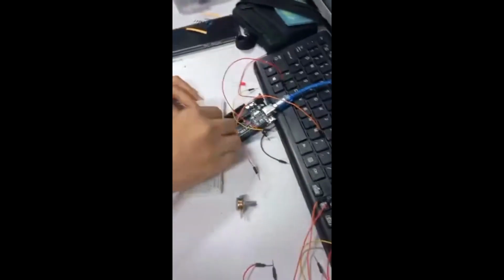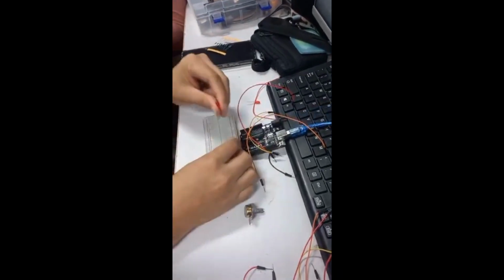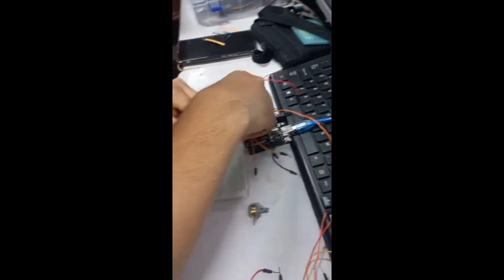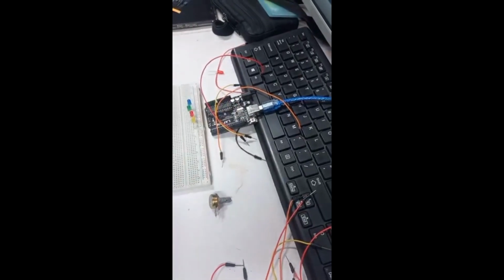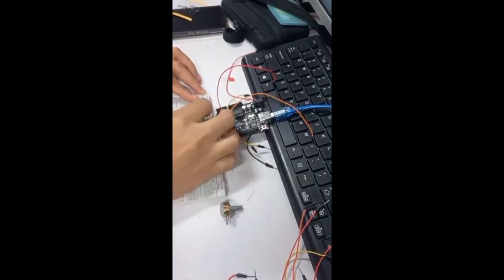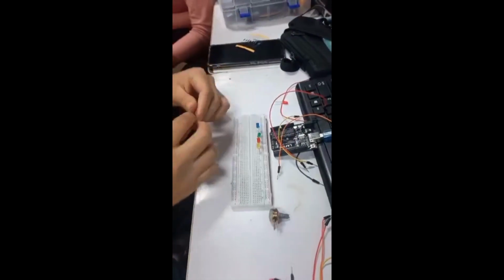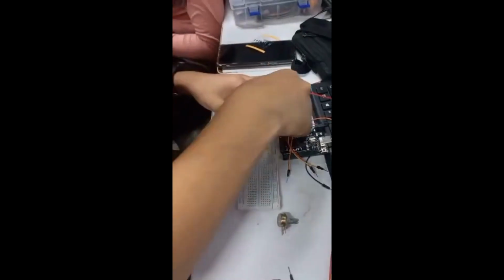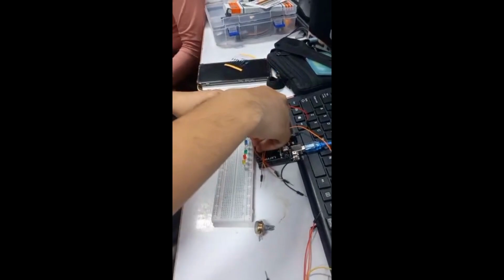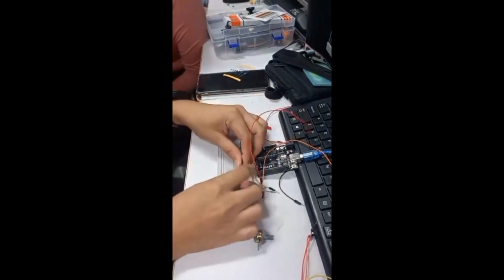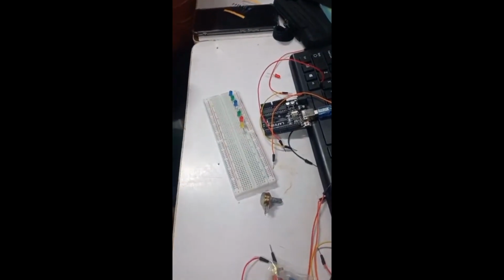Wiring wizardry, building the light bridge. Follow the wiring diagram. Ensure you have the correct one to create the necessary connections. Connect the LDR's 2 pin to a voltage divider circuit with a resistor. This circuit creates a stable reference voltage for the Arduino to compare the LDR's changing resistance to. Finally, connect the voltage divider's output point to an analog input pin, A0 in this case.